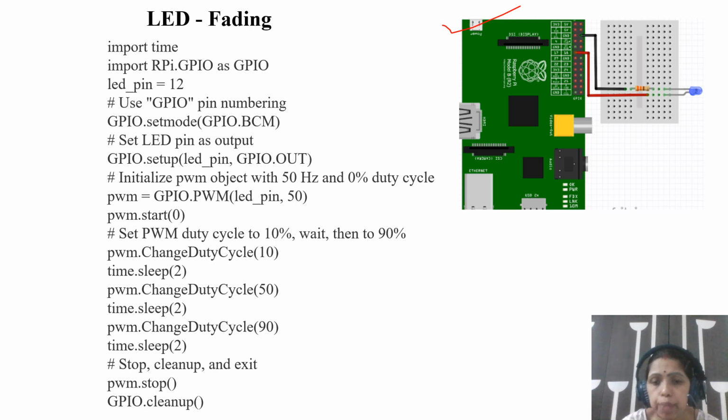Okay. And here, first you have to import the libraries and packages. So import time and import RPi.GPIO. I have already discussed this. You do not write the entire module and package name like RPi.GPIO throughout the code. You give it a short name: RPi.GPIO as GPIO. So instead of writing RPi.GPIO, you can write GPIO in the entire code when you call a sub function from the GPIO. I hope it is clear to you.